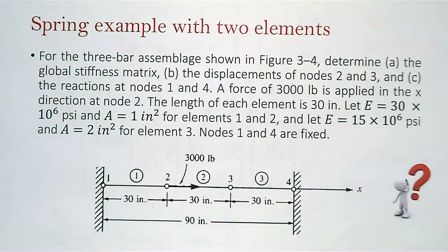So for example, for element number 1, we can say that little f1x, little f2x equals the 2 by 2 K matrix for element number 1 times u1, u2, right? It's exactly how we got it from the free body diagram, but you can just use that formula, avoiding doing the free body diagram again.